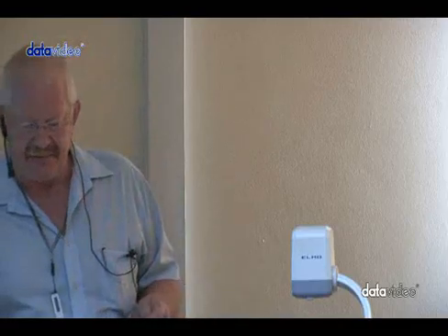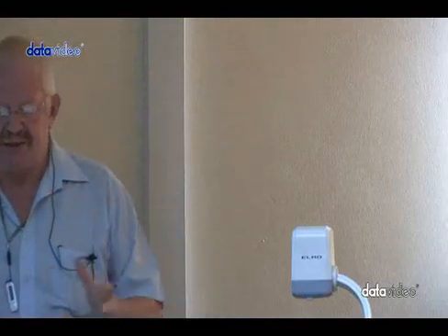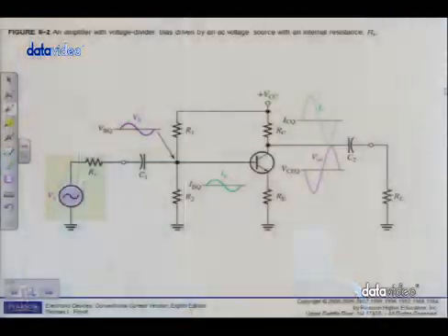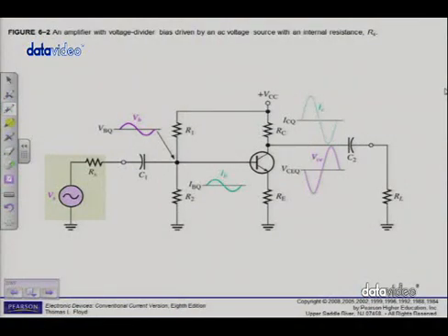Alright, just to refresh your memory again, you were introduced to a linear amplifier in Electronics 1 in chapter 5. It's basically what you also looked at. If I look at the specific circuits, I see that you have done biasing circuits in chapter 5. What sort of biasing is used here? What type of biasing is used in the specific circuit? Voltage divider bias. Now, I can see that clearly because there's my supply, there's R1, R2 that is providing my voltage divider bias so that I can get a certain VB here, which will also, of course, give me my IBQ.